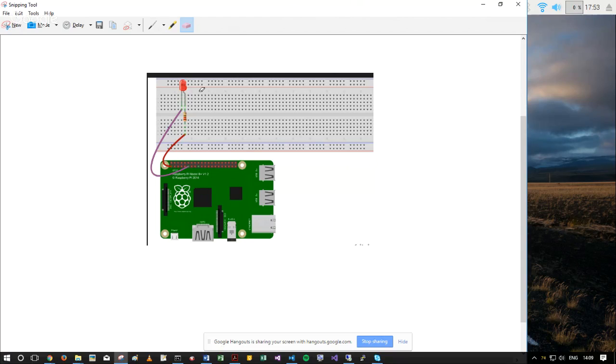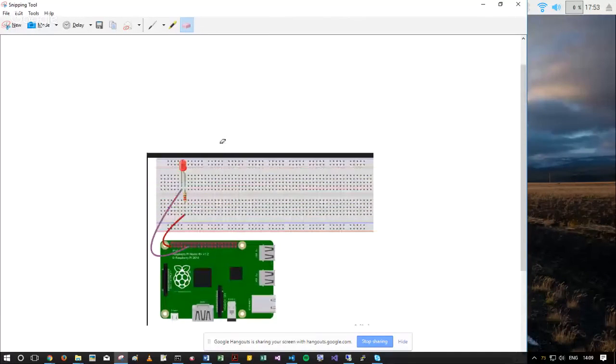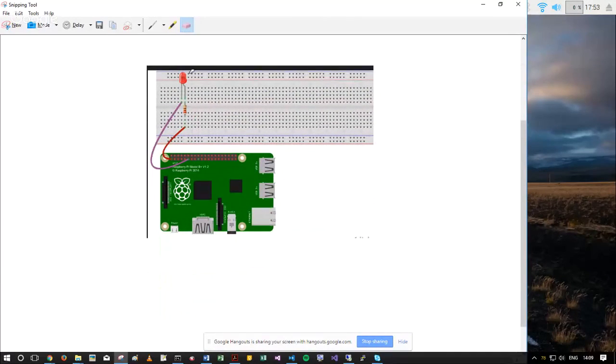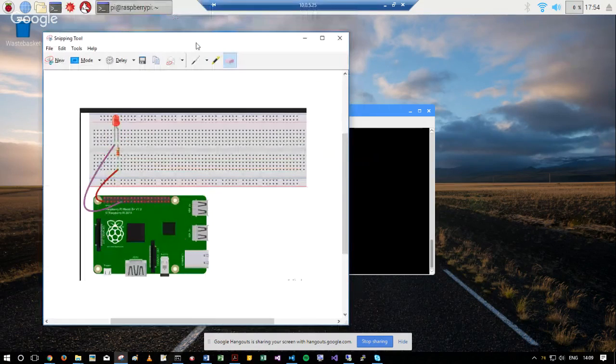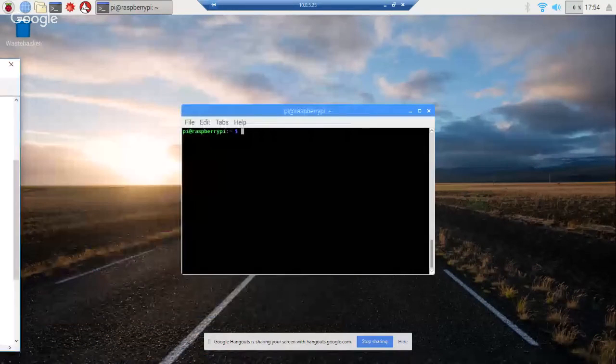In this case, you would calculate the voltage drop across each of the things to make sure too much voltage isn't dropping over anything. You want not too much and not too little, because if the resistor is too large, it'll have a larger voltage drop across it, and then the LED wouldn't light as bright. But if it's too small, too much current could go through the LED, or through a more sensitive device. So the calculation of the circuit is extremely important. So that's it for the circuit.